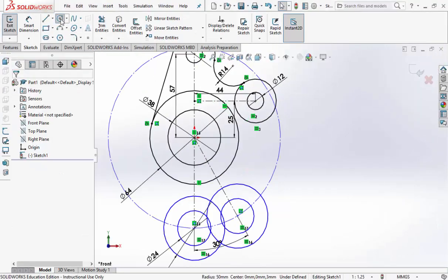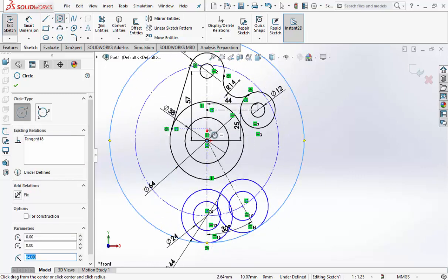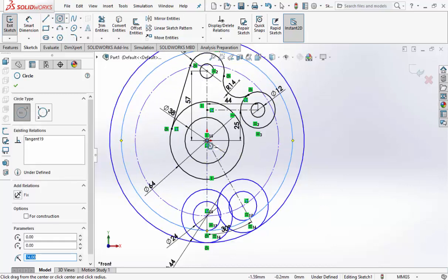You draw the circle tool from the origin. You just snap it tangent to the bottom. Draw a second one from the origin, and snap it down to the bottom of that one. And go from the origin a third time to the top of that one.